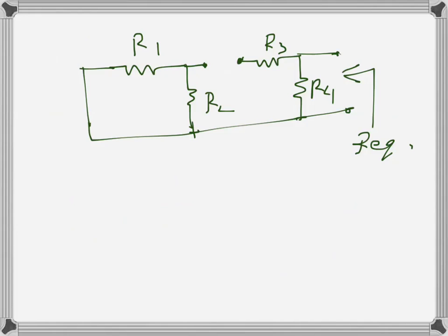For this particular circuit, the current source is made inactive by making it open circuit, because in order to make it inactive we have to make the current through it zero, and that's only possible if it's open circuit. Similarly, the property of a voltage source is that it maintains a fixed voltage, but if we make it short circuit, that's the way to make the voltage source inactive. So for this particular arrangement, since there is a break here in the circuit, the equivalent resistance will be just R4. But this is just because it's very simple for this particular arrangement.